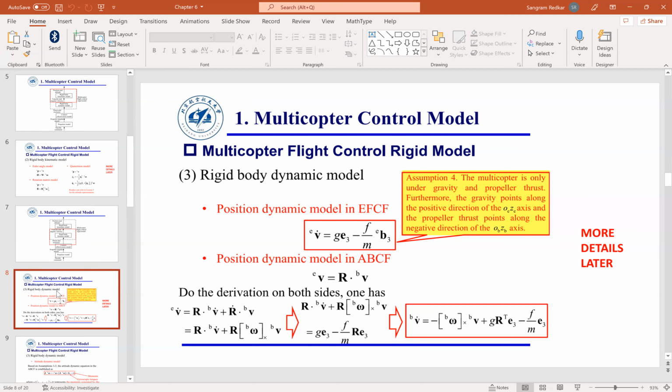And then you're going to have the force on the aircraft. It could be the thrust. It could be some sort of aerodynamic force, lift or drag. That force has to be in the aircraft body reference frame, because that is the force on the aircraft. So air cannot give you lift in the downward or north-east-down direction in the Earth-centered, Earth-fixed frame.